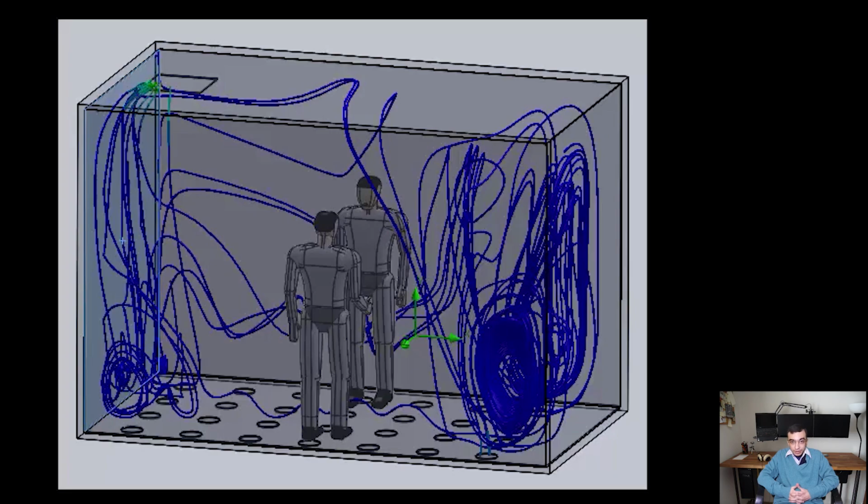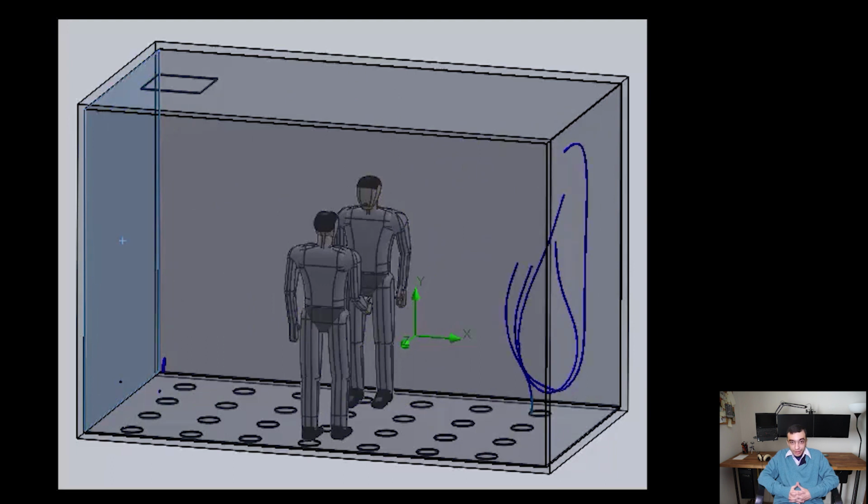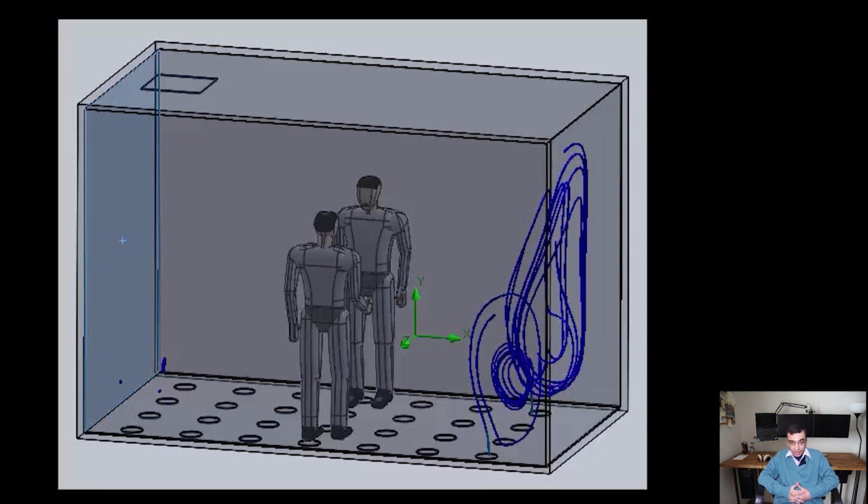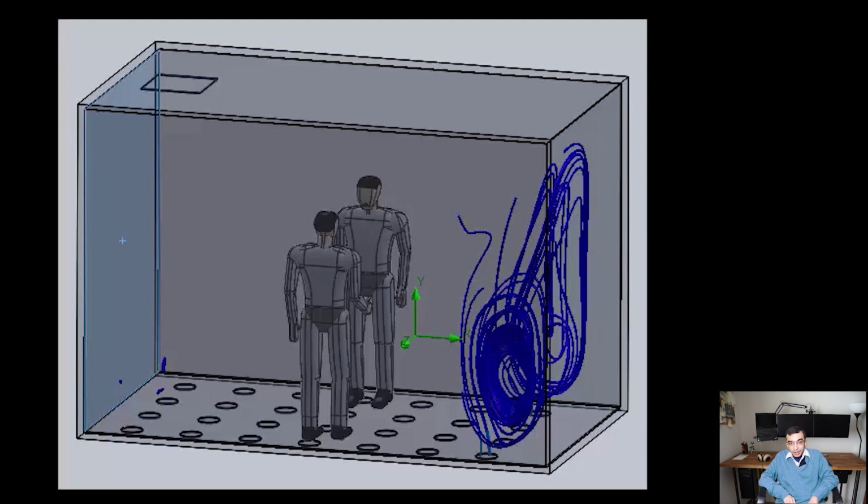The operation of this system is as follows. The air is supplied through the floor plenum and is returned through a small false ceiling. The air is supplied at low velocities, which causes no mixing issues. Space for utilities is provided by the floor plenum.